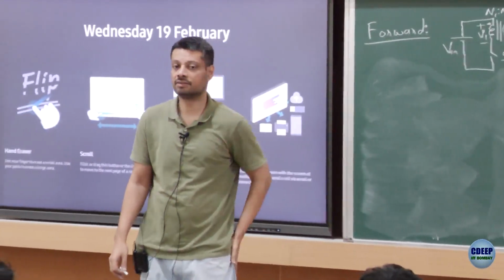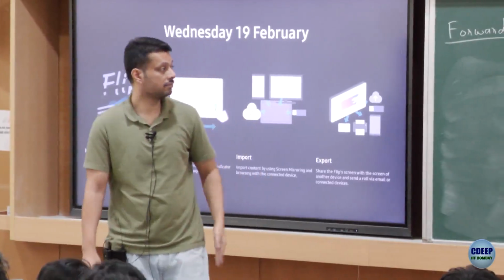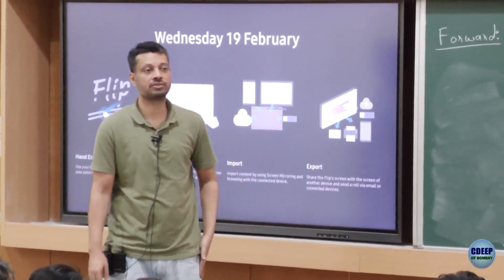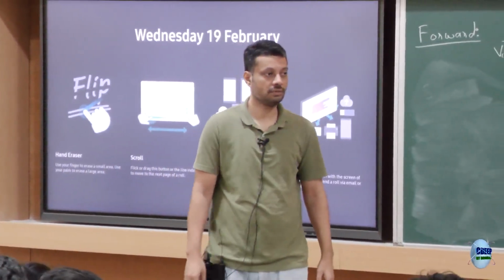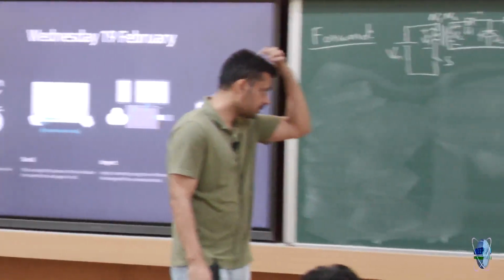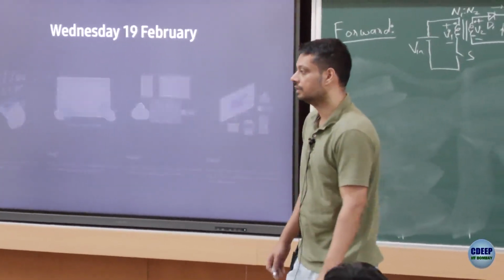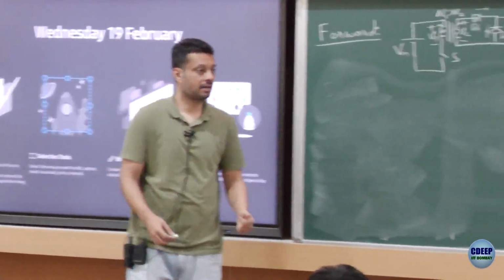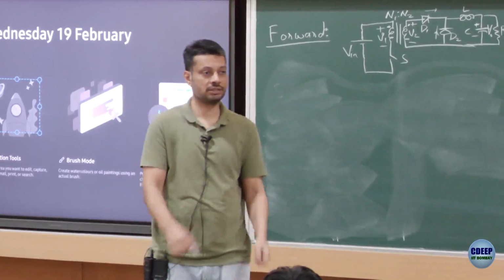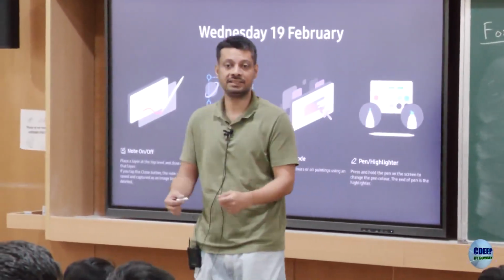Anything wrong? Looking at V1, do you feel anything is wrong? What is the average voltage across the transformer winding in this case? It's positive, right? If you apply a transformer with a DC voltage, what will happen?